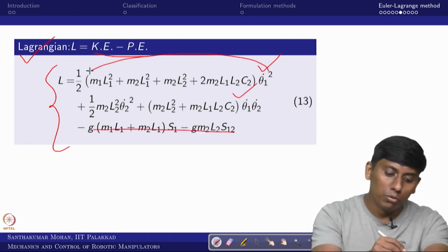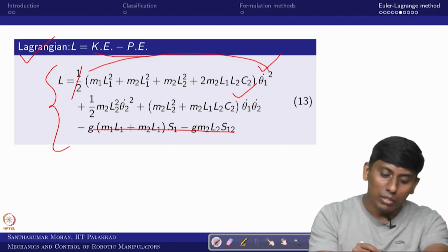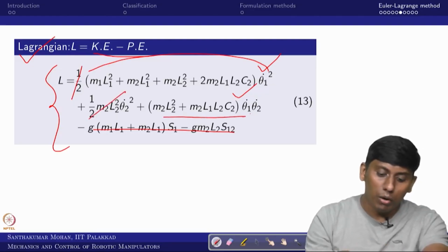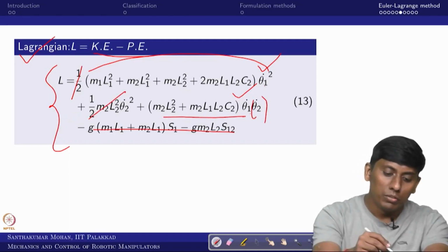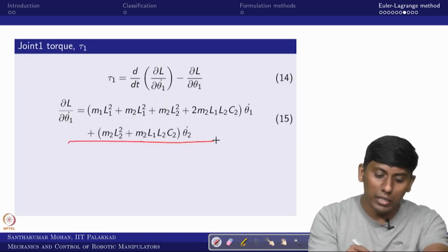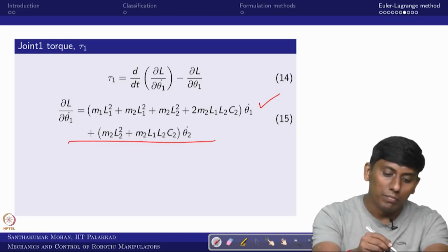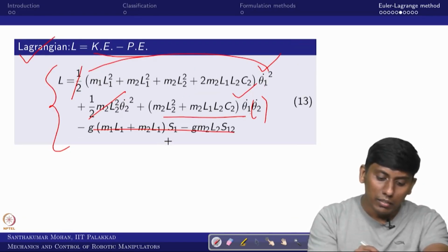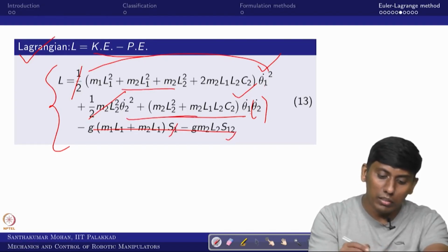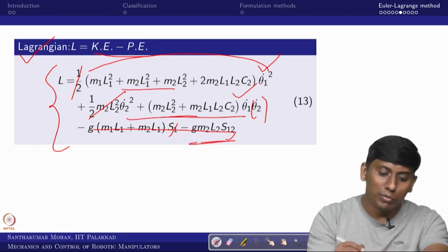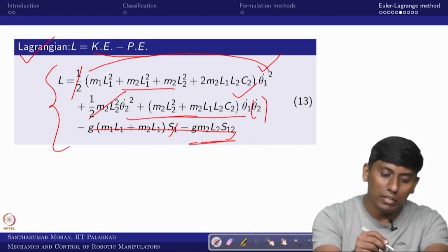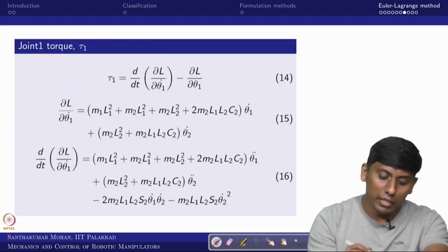In the sense this 2 goes out, and here you can see that θ̇1 is coming only here, so this goes out. So θ̇2 remains, and here θ̇1 remains. So we can see what that partial derivative is. Similarly you can take ∂L/∂θ1. Unfortunately, θ1 is here, so in these 2 equations there is nothing, so you can take it as 0, and these 2 relations are what remain.